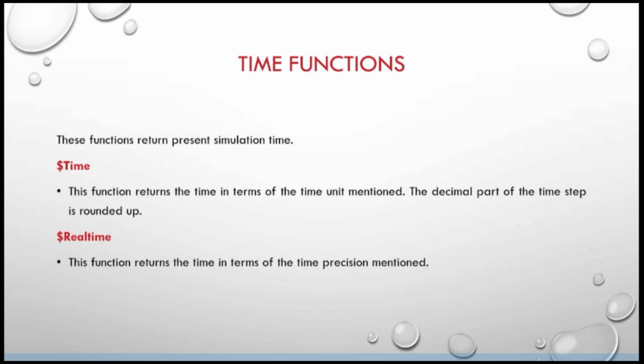Okay, so this is about time scale. Apart from time scales, you have some time functions to know the simulation time. We have already discussed them when we discussed data types: $time and $realtime. To know at what simulation time your statement is being simulated, you will use the time function called $time. To know the floating-point value of the time, you will use $realtime. So these are the basic time functions in Verilog.